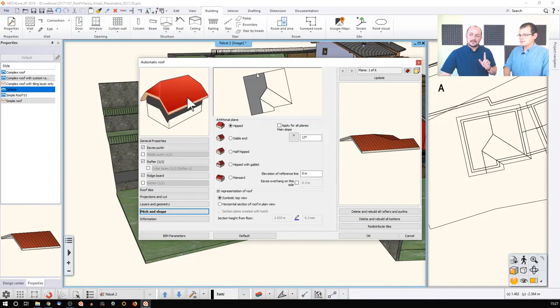You can actually select a roof plane which is not visible as well. See, I have disabled this roof plane, but it's still there. The plane count is still 6. There also, you can navigate 1, 2, 3, 4, 5, and 6. They are still there. So in that case, if I would like to go back and, for any reason, turn this back to hip, I can just do that and it will go back. So disabling this, update, and then going back to the original topic.